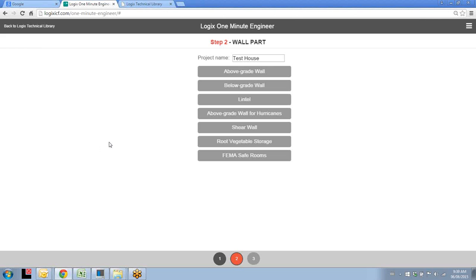Let's talk about lintels. Now lintels are the beam, the structure that you're putting over top of an opening. It would be a door opening, like a garage or a main floor door, or it could be a window opening. And essentially, what the lintel does is you place the lintel over top of the opening, and it's designed to replace the strength that wall has lost when you remove the wall area of the opening. You create the opening, you remove concrete, and so you've got to make up for that lost wall structure, and that's what the lintel does.